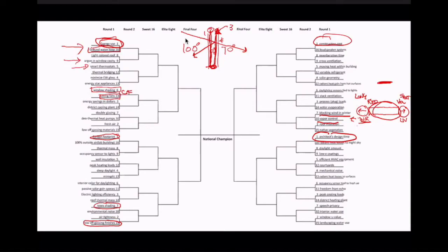What you're feeling there is not the brick heating up the air and the air touching your skin. What you're feeling is the radiant heat transfer from the brick, which is hotter than your skin. Any two bodies that see each other, where there's nothing in the way like a tree, will exchange heat based on how much warmer one body is than the other, and also based on how big the hotter body looks compared to the colder body.